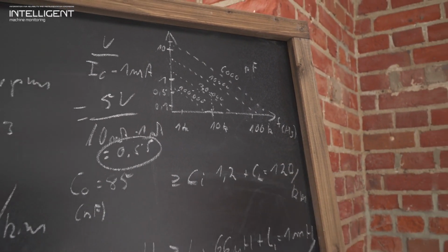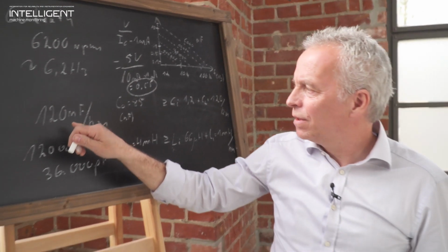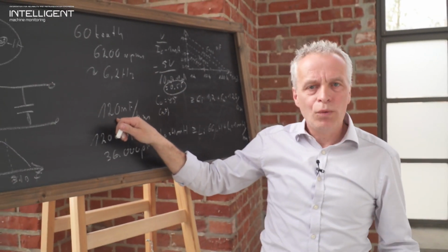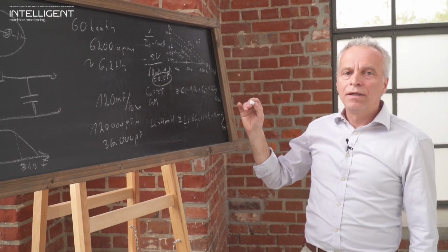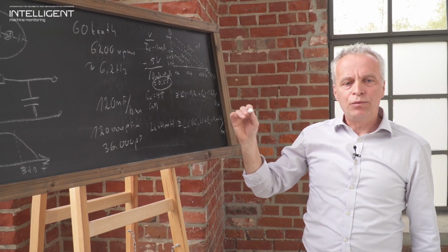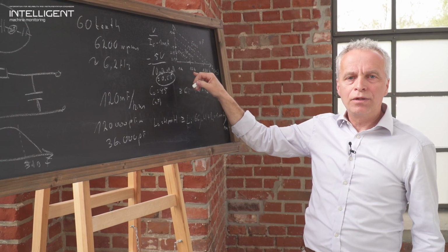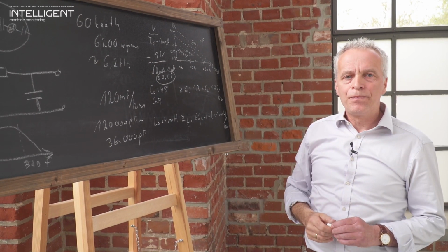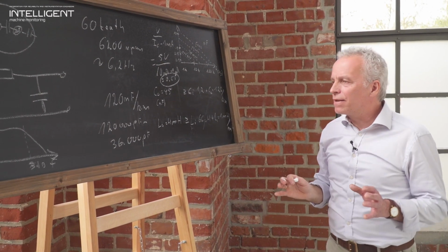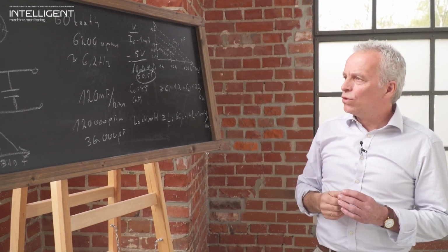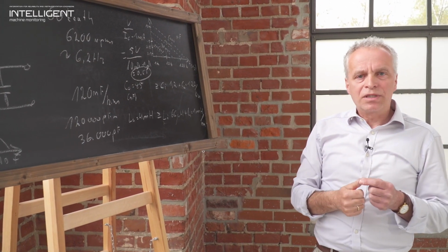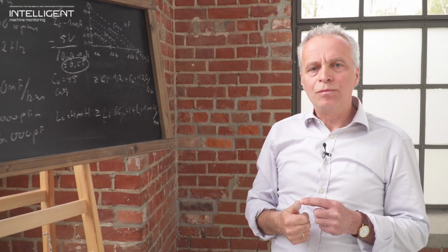So we know for this given cable with this given capacitance, we are fine having a length of 300 meter. And we do not have a cutoff frequency lower than 10 kilohertz, the 10 kilohertz that we want to measure. So this is regarding the signal quality. If I resume, we need, from our experience, 10 kilohertz to do a decent monitoring.